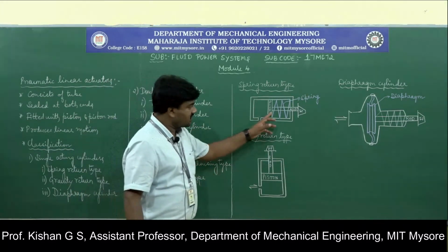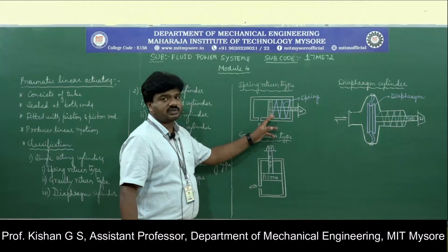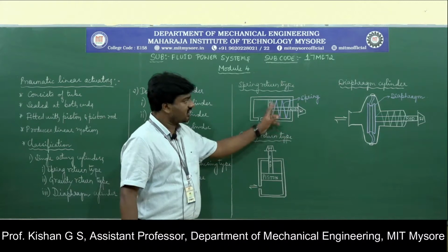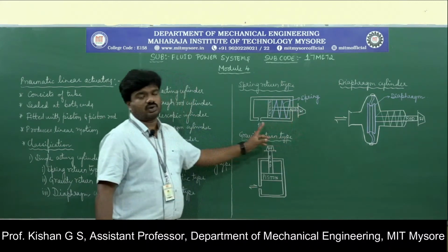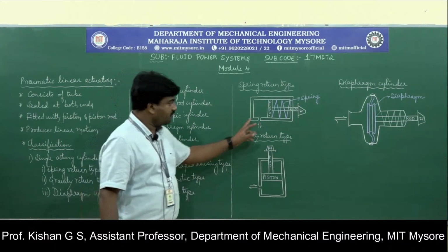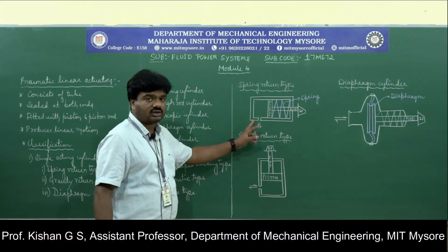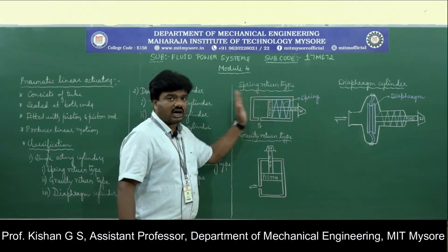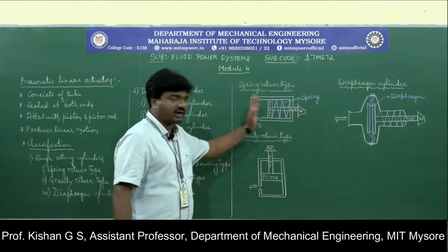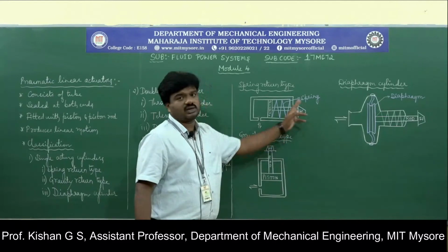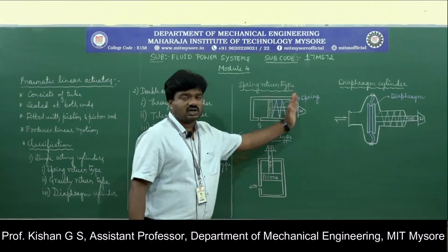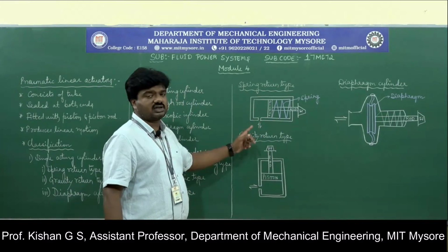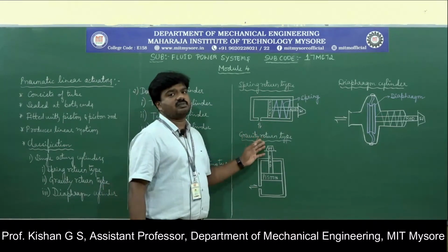So what we are doing is we are going to have the assistance of a compressible spring on the piston rod end, which is in contact with the tube or the cylinder body, such that once the compressed air enters through the inlet or the port into the cylinder, that leads to the movement of the piston along the linear direction from left to right, such that it carries the load W. Once it carries the load, the supply through the port or through the inlet, whatever opening we have here in the cylinder, that supply of compressed air will be cut off.